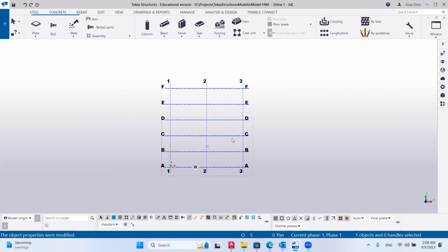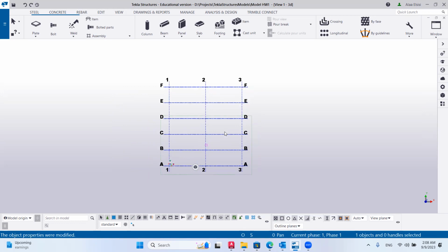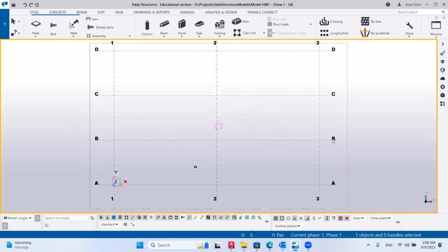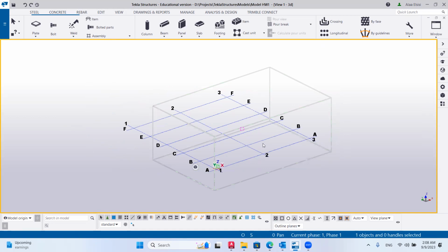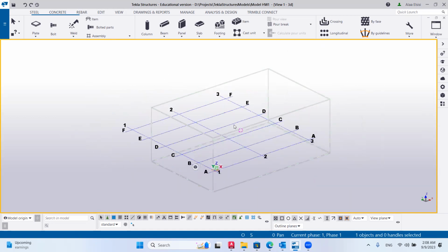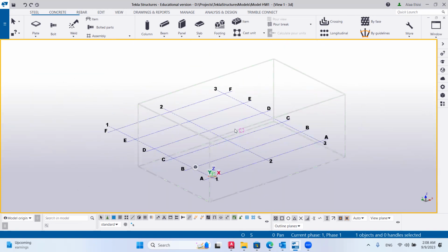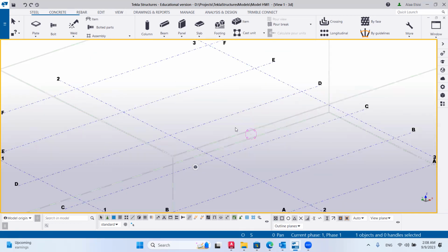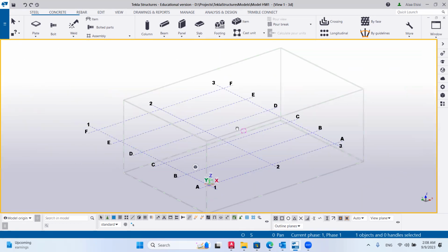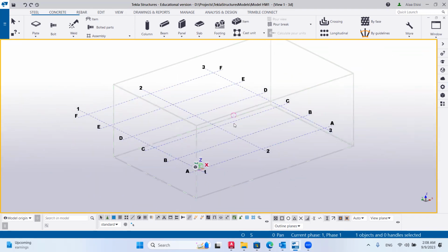Okay. Now before we go again to the grid, I need to show you some very important options. Again, we talk about Control P, which switches between the two-dimension view and three-dimension view. Also, the middle button of the mouse zooms in and out like this. If you scroll it, and if you click on it and drag in any direction, it will pan the view like this.